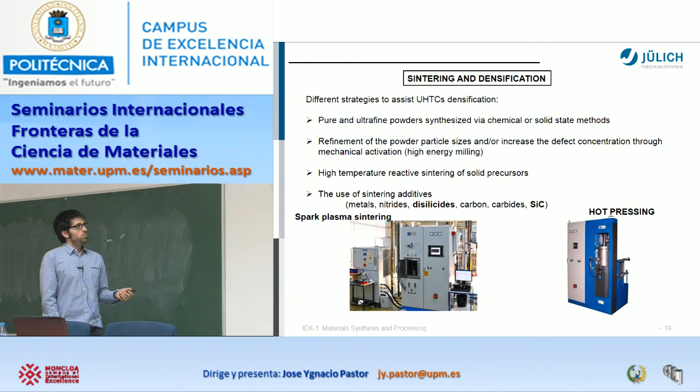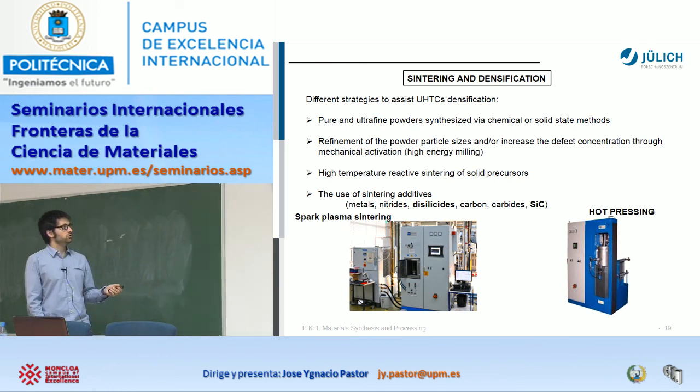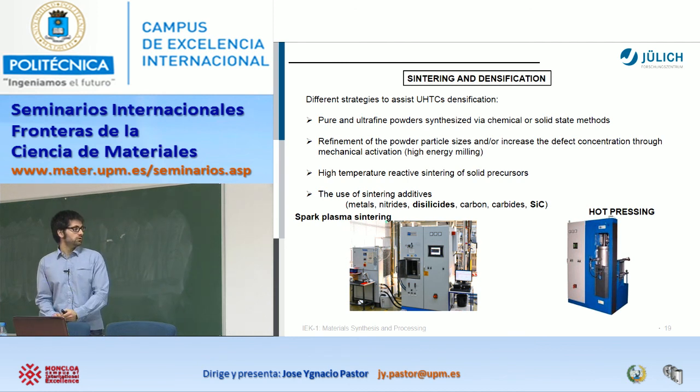Okay. One of the best methods, and this Spanish group in Extremadura is working very hard on it, is to try to obtain the highest purity possible in your powder, and also go, if possible, into the nanoscale. Of course, if you reduce the size of your starting particle, there is more energy on the surface, and then the reactivity starts at lower temperature and is easier.